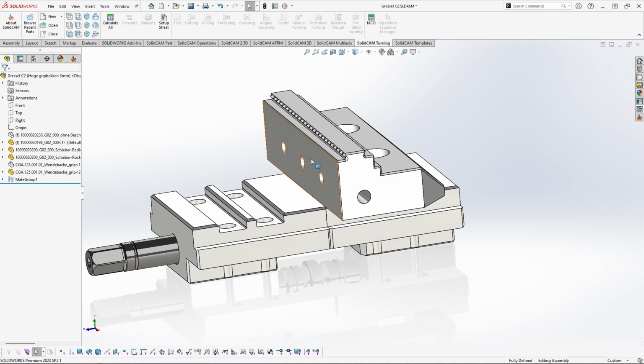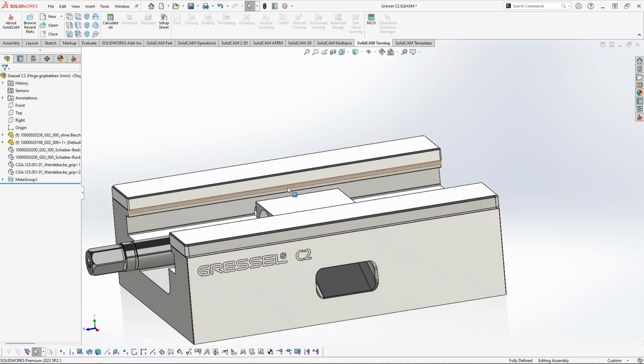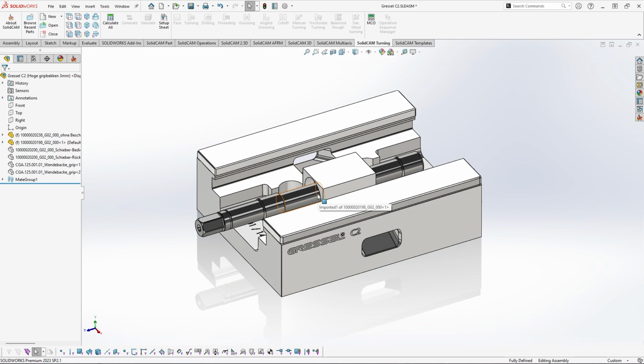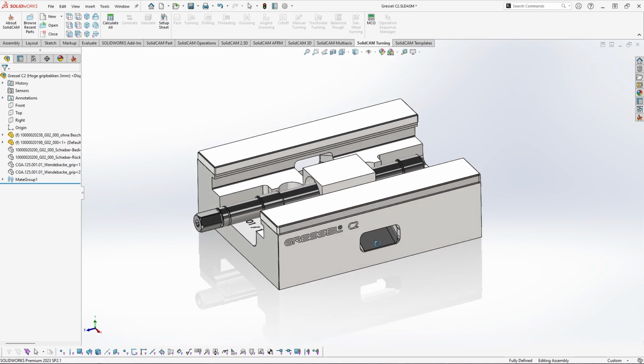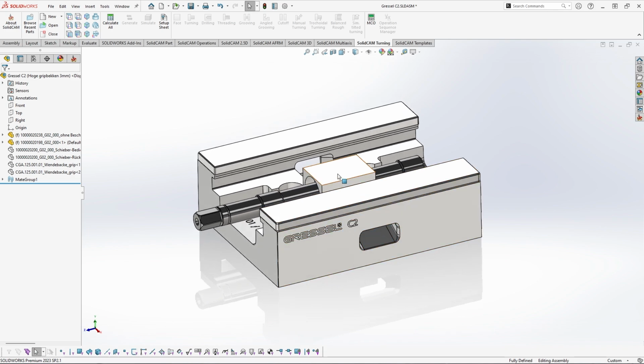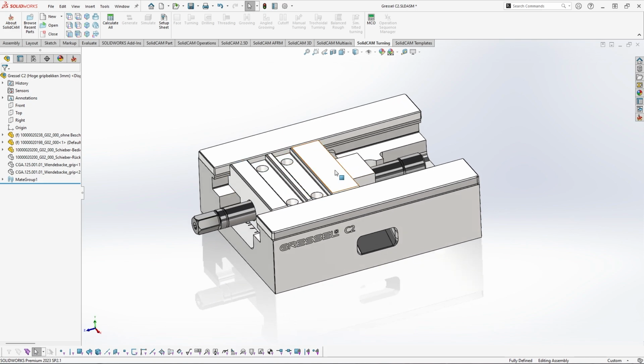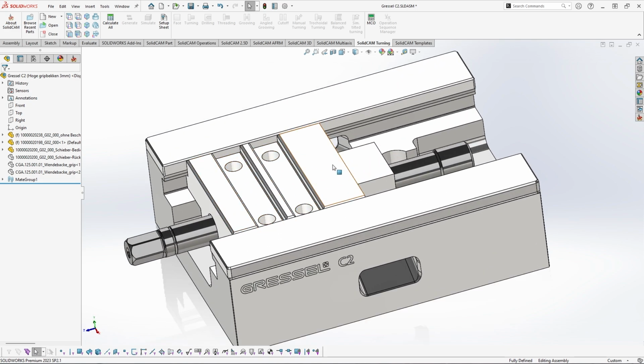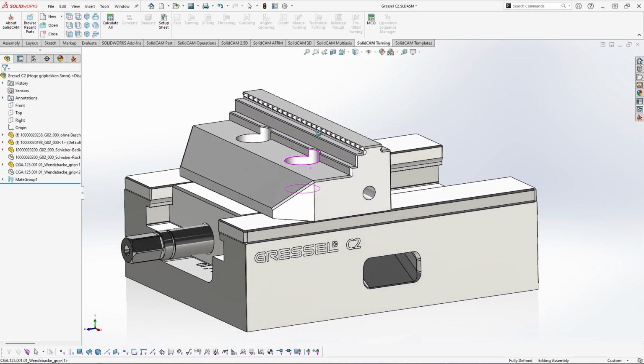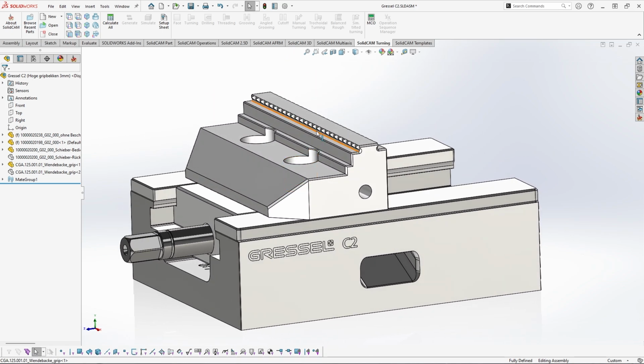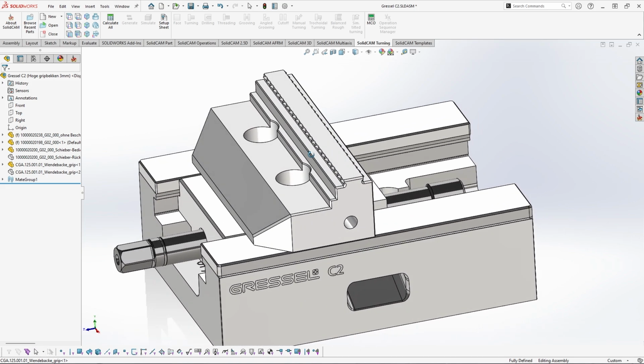Okay, my first geometry will definitely be this, which I'm going to call the main body. It will consist of one coordinate system. On top of it, there will be one linear guider on my linear axis. This linear axis will also be patterned, which means I'm going to create exactly one and mirror it, so this one moves together with this one. And on this, there will be a jaw itself. So these are the three components that I need for this vise.